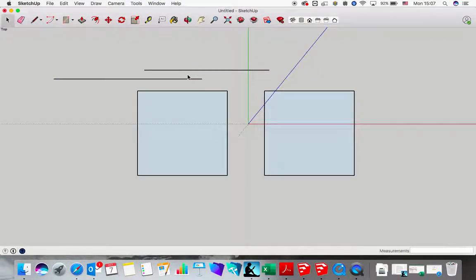Another thing that's good to know before I let you go is the tape measuring tool. So if ever you draw a line and you are unsure of how long it became, you can click on the tape measuring tool, click on the starting point and the end point of the line, and that will show up here in your length. So if I do that again and you have a look at the length box here to here, it also shows up next to the tool, 6,579. That way you're always sure that you're drawing it correctly.